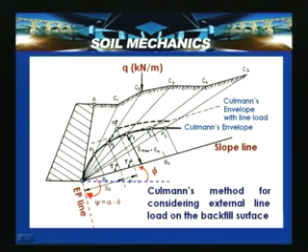So here when you look, we have drawn lines like BC1, BC2, BC3, BC4, BC5 passing through the heel of the wall. B is the point here. Then once we have found the weight of this wedge ABC1, we represent the weight of this wedge along the slope line to a suitable scale. Similarly, determine the weight of the wedge ABC2, determine its scale and then put it on the slope line.